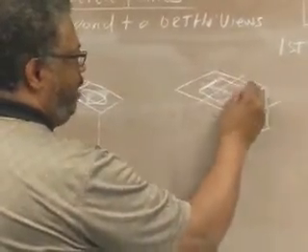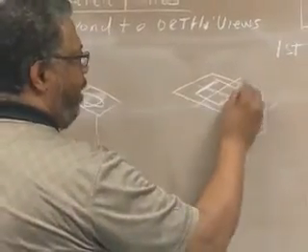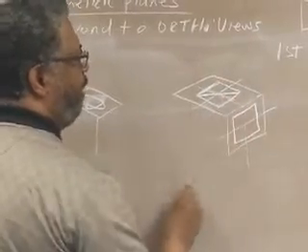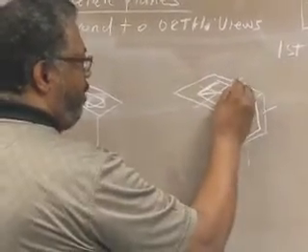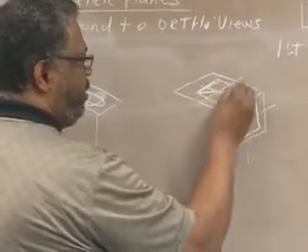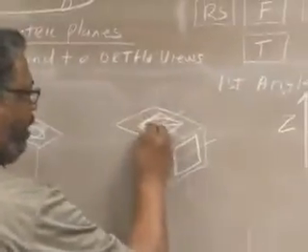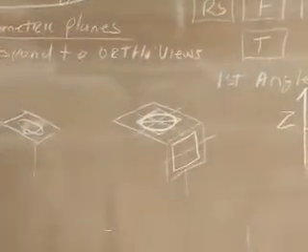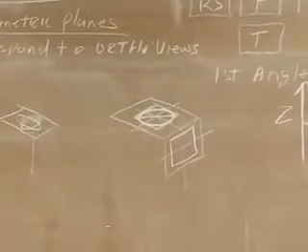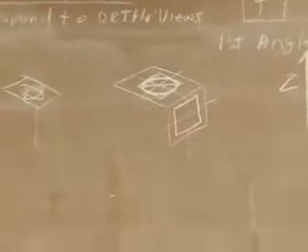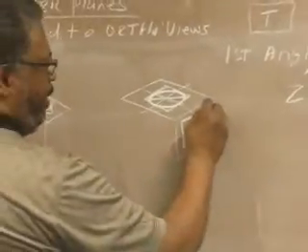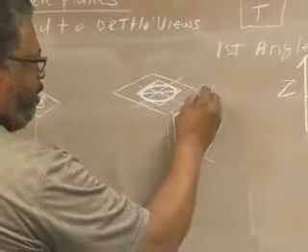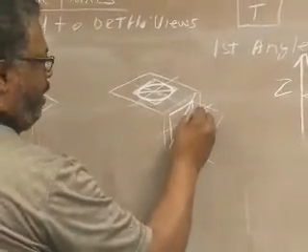So this helps with the orientation of it. Once I locate this and produce a square, then I get that diagonal here and that diagonal there. This diagonal is the longest distance, so that would indicate that my ellipse would sit like that, right there. That's the correct angle of my ellipse. If I look at it from the right side, then this distance here is longer than this distance here, so that's my major axis of my ellipse.